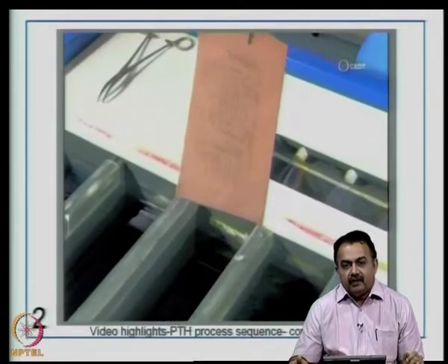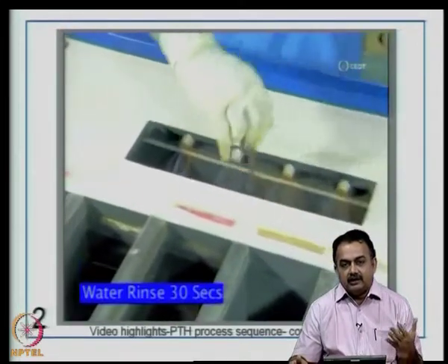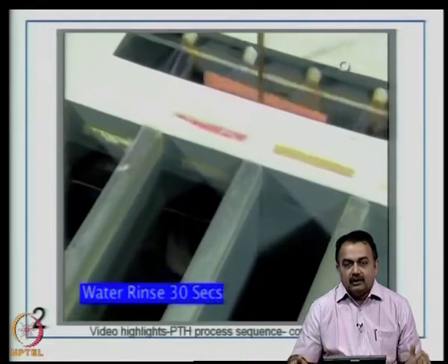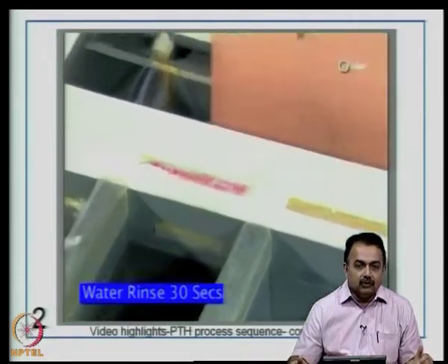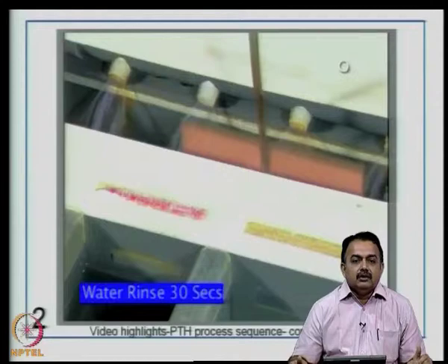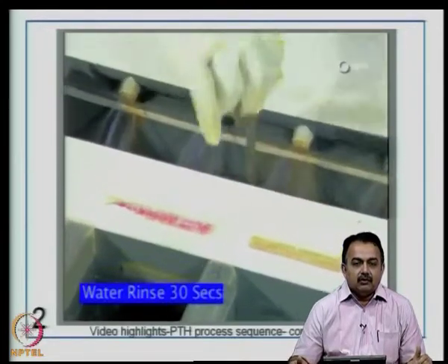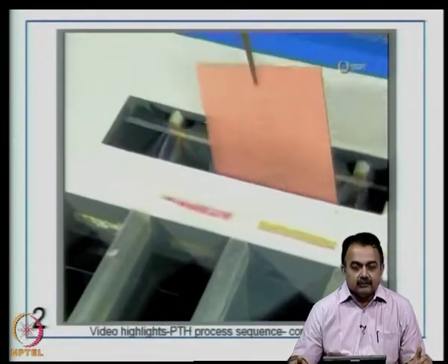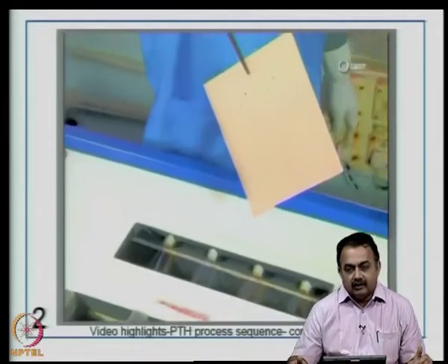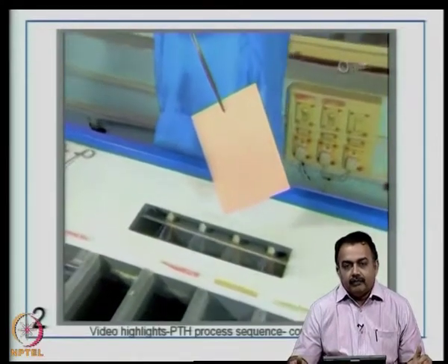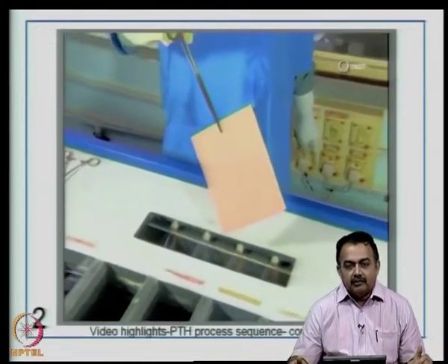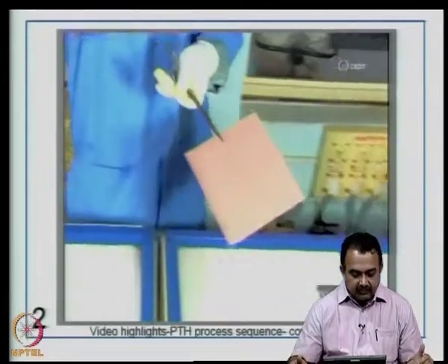Mind you, we are activating the surface as well as the through hole walls. We can't selectively do it for the hole walls. So, any process here will cover the hole walls as well as the surface. That will ensure good binding and provide better connectivity from the top copper surface to the bottom copper surface.